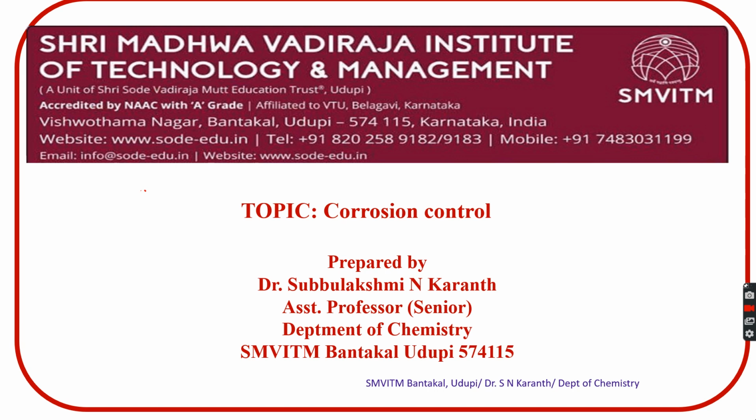Now, the corrosion control method mainly depends upon factors such as the type of structure, the nature of the corrosion, the residual stress in the fabricated article, the nature of the environment, and other factors that decide the corrosion. Based on that, we have to decide the corrosion controlling method. There are four major methods we adopt: protective coating, use of corrosion inhibitor, cathodic protection, and anodic protection.